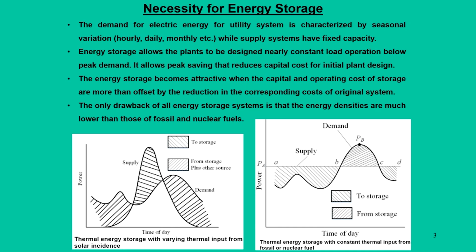So, in order to run the plant continuously with steady energy, we require the main plant to operate at base load, and during off peak hours energy can be stored, and this stored energy is utilized further to cater to the peak demands by the users.